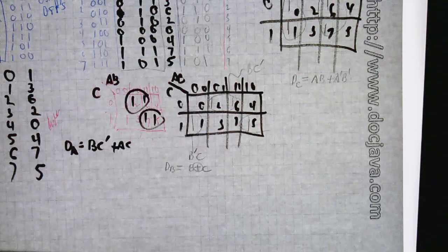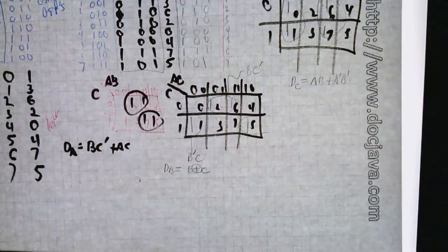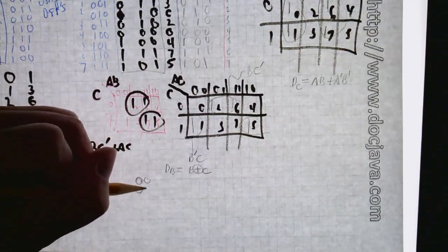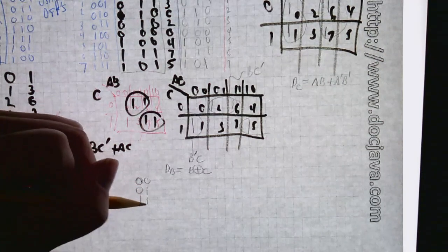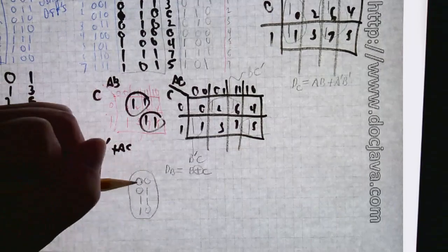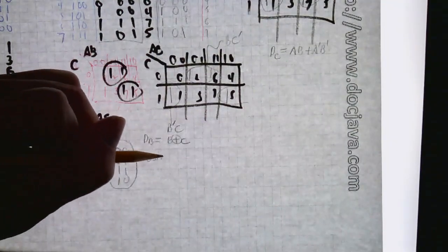It should have just been implement the 2-bit sequence, which says, oh gosh, 00, 01, 11, 10. That's a much simpler sequence, right? Implement that sequence using toggle flip-flops.